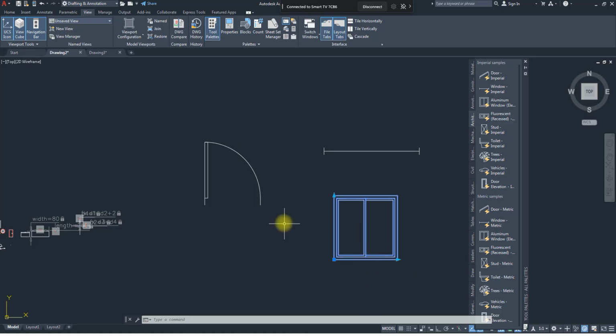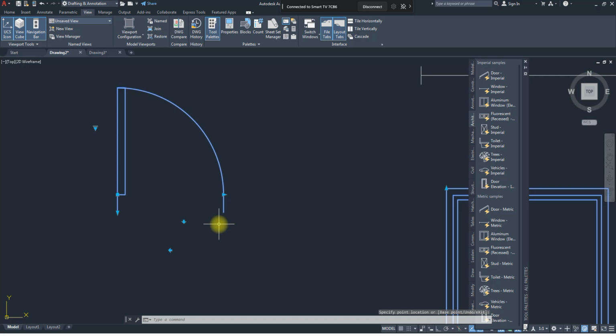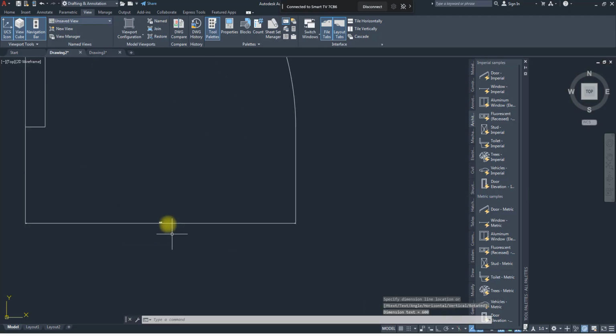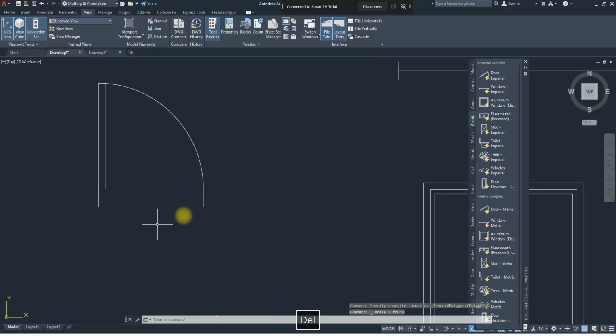Okay. So the thing with this door is it comes with preset sizes. If you click here, you can see all those lines. They are the preset sizes we have. So it was created for those preset sizes. What you can do in your own case is to check the dimension. If I bring it to the smallest door, I can bring my linear dimension to check what this dimension is. So this is 100. So you will see 900 there. And this one will be 700.